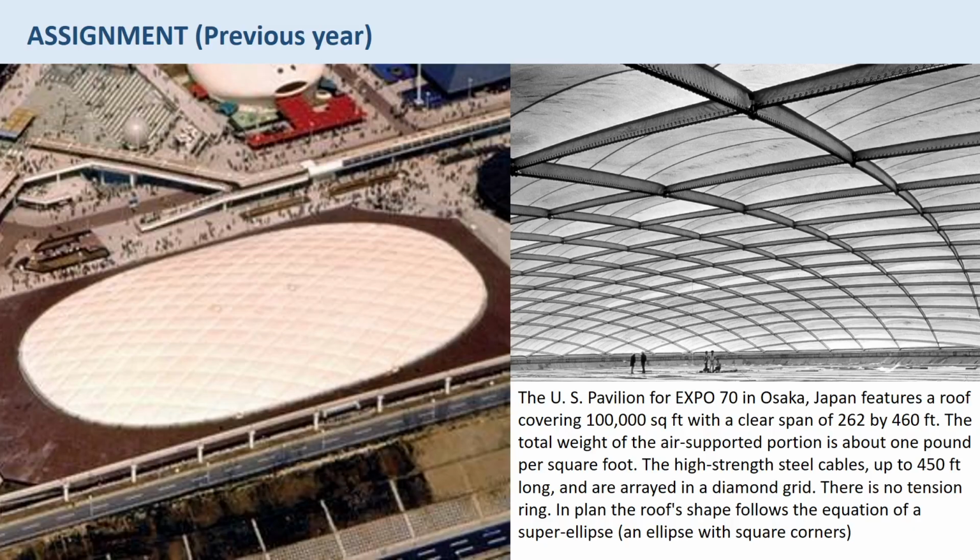In an air supported pneumatic structure, air pressure higher than atmospheric pressure supports the envelope. Airlocks or revolving doors help in maintaining the internal pressure. Air must be constantly provided in such structures. The lifespan of such structures is 20 to 25 years. They are either anchored to the ground or to a wall so that leakage is prevented. They have relatively low cost and they can be installed easily.